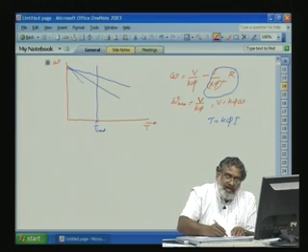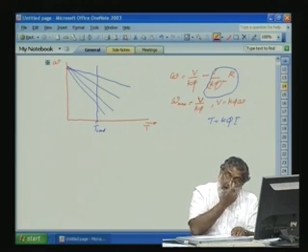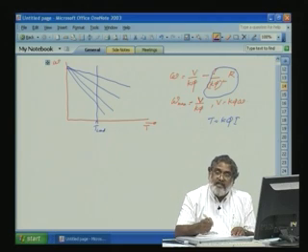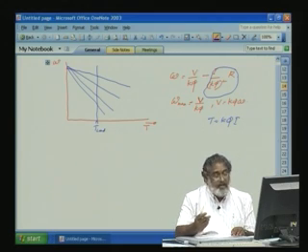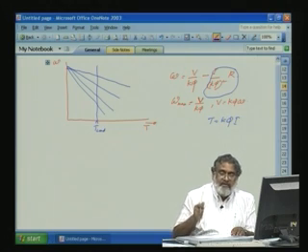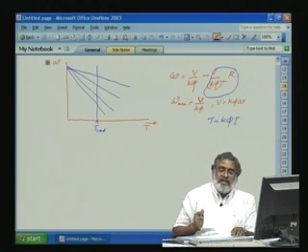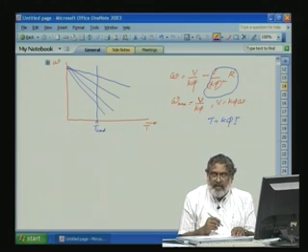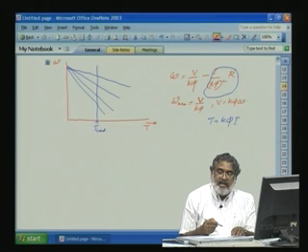So, for different R, for the same load, by introducing more and more armature resistance, we can control the speed. This type of speed control we have done before, where we can see with the lever while we are increasing and decreasing the armature resistance. That way we can increase or decrease the speed by varying the armature resistance.